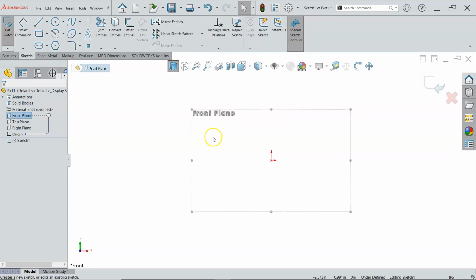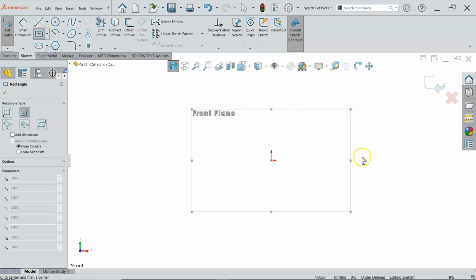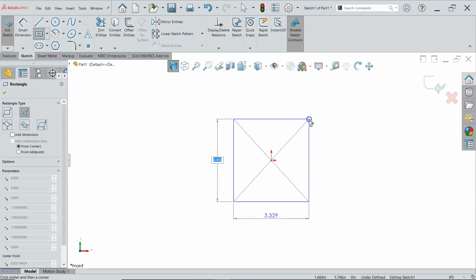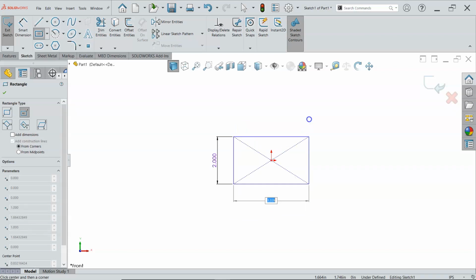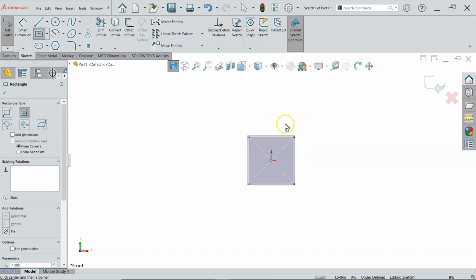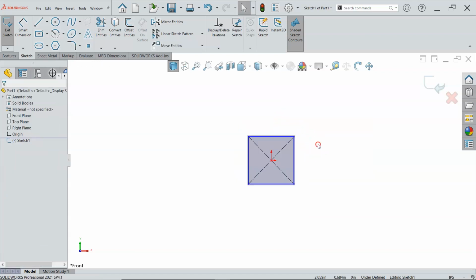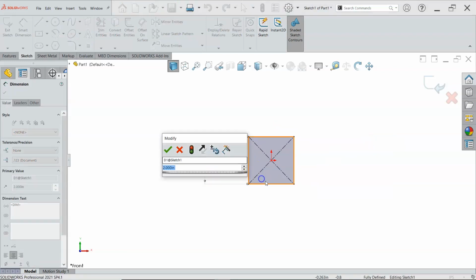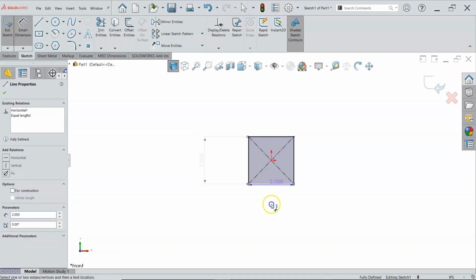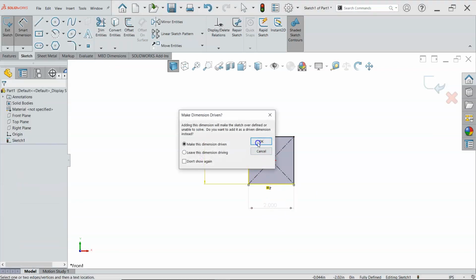So in my part, I'm going to create a sketch for a center rectangle, and I'm purposefully putting the origin at the center. If I remember to hold down the left button, I can go 2 by 2, and it did not add it, so I still managed to not get those in, but it did put my sizes correct.